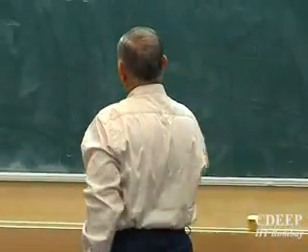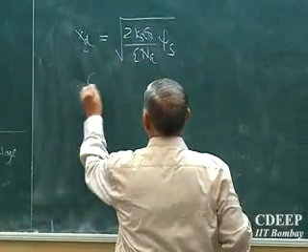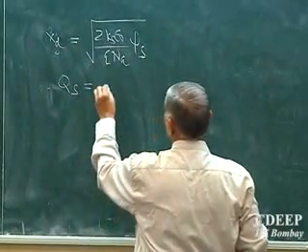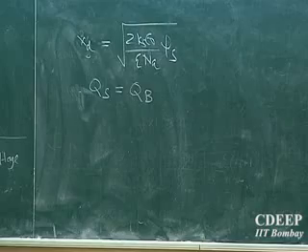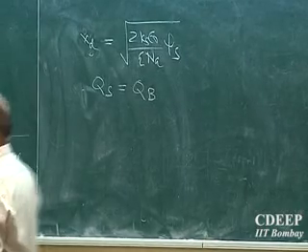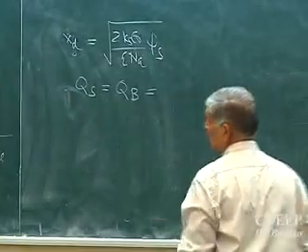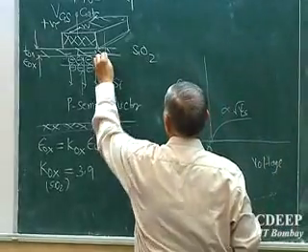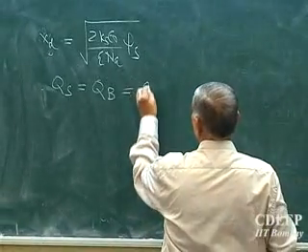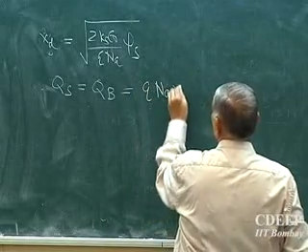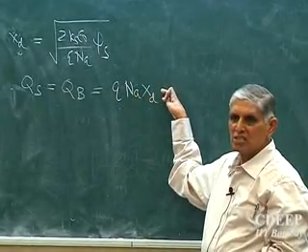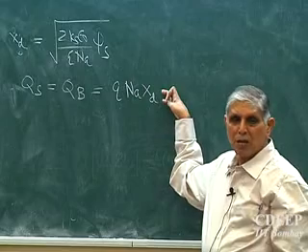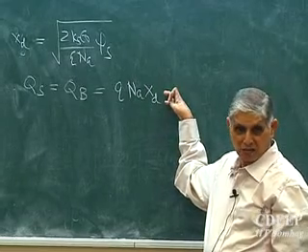Now we know yesterday, since XD is proportional to psi s, the semiconductor charge essentially we call it bulk charge. The word bulk is used when the charges are due to depletion. So the bulk charge is how much in this case? If this is your XD, how much is the charge there per unit area? It is q N_A XD per cc into distance, so per unit area. So this is the bulk charge or charge due to the depletion layer.